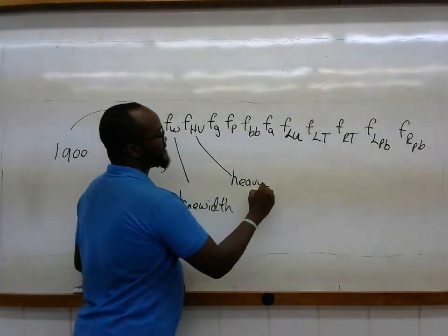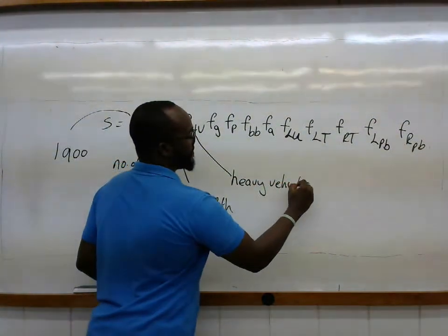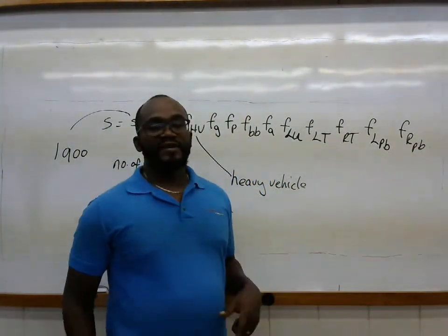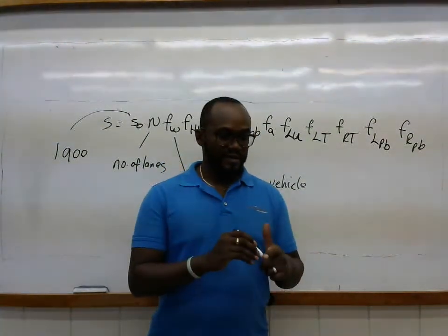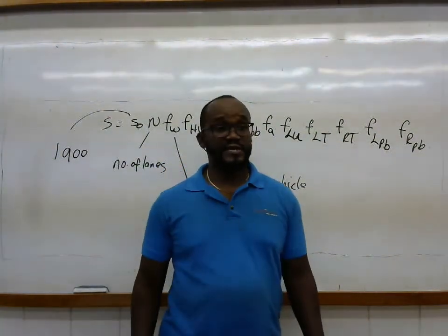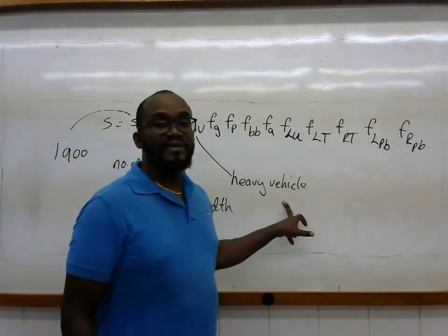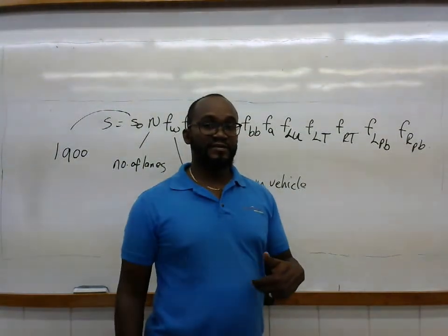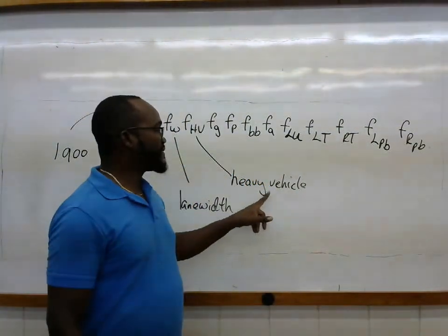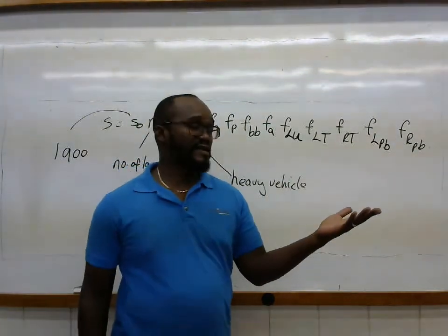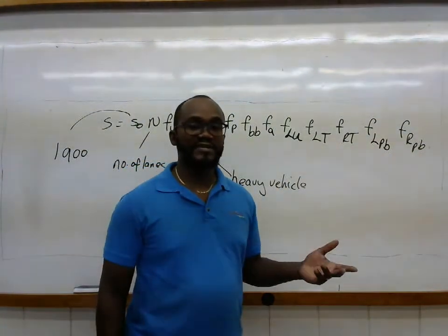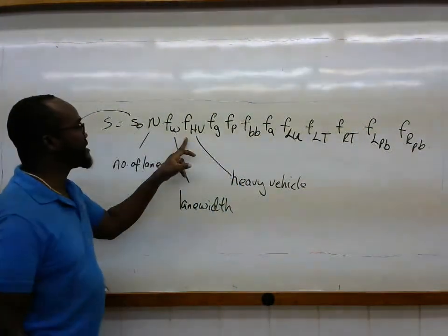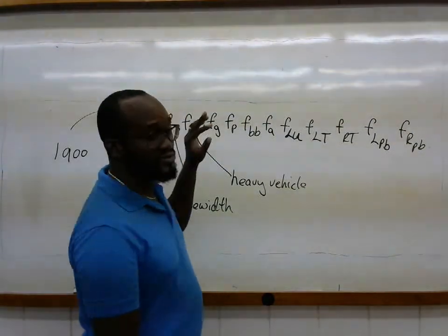The heavy vehicle factor. This should come as no surprise. The more heavy vehicles in a traffic stream, theoretically, the less the saturation flow through the intersection. So you recall that in the classification, you're required to count heavy vehicles. Well, this is the reason why. Heavy vehicles have been statistically shown to have an impact on speeds through an intersection, on capacity and flows, etc. So as part of the theoretical saturation flow formula, there's a factor to govern down, so to speak, the S0 value.